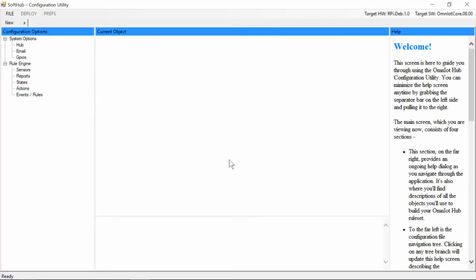We'll create a new configuration file and then create the few objects and rule set we'll need to implement our example scenario. We'll create 3 sensor stream objects to describe the sensors we want to connect to, and in doing so we'll also define 3 events to be queued whenever a new packet arrives from the individual sensors. Then we'll create 3 associated publish data action objects to publish the sensor data to our target MQTT server, and lastly we'll create the 3 rules that will tie the new packet events to the publish data action objects.